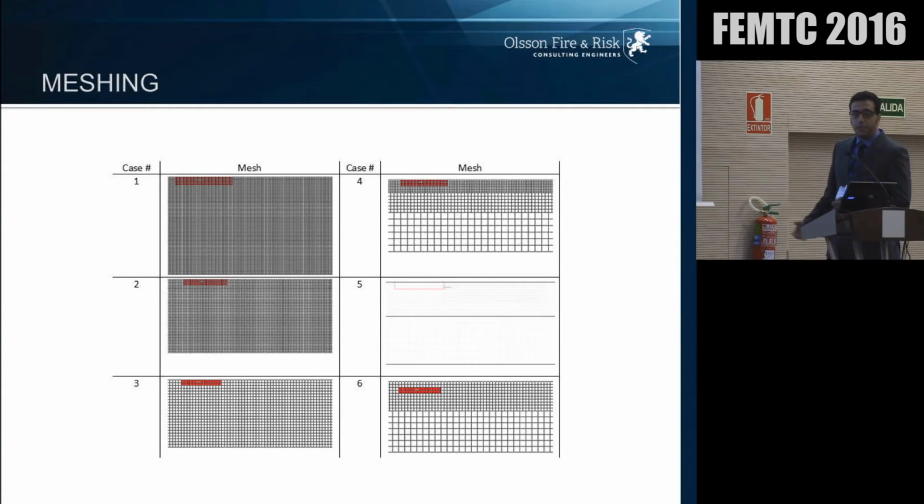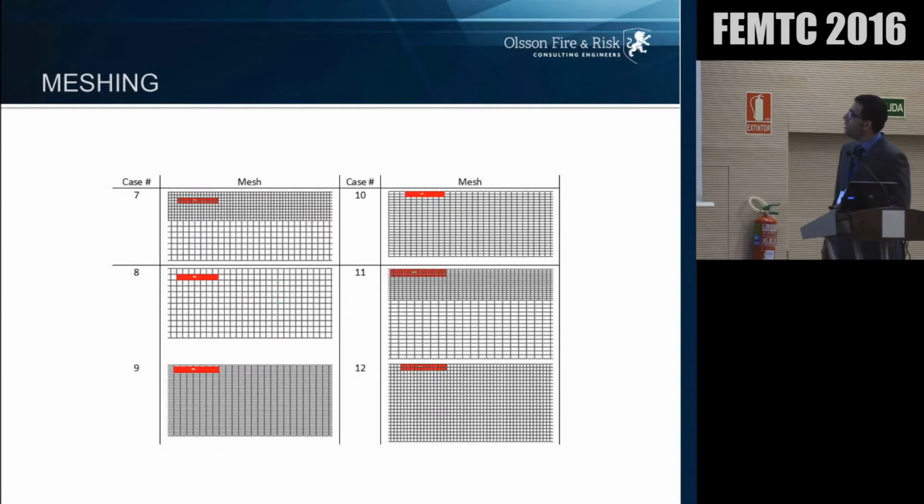Option number 5 is the embedded mesh, where you have overlapping of the mesh. 6 is just a very traditional mesh, where you just refine it once. Number 7 is exactly the same as before, but we have a bit finer mesh as a base mesh. And number 8 is a very coarse mesh, which is the 250 millimeter mesh. Number 9 is we start to vary the aspect ratio of the mesh. So this is a 4 aspect ratio. This is a 2 aspect ratio. This is maintaining the 2 aspect ratio with 2 different mesh refinements.